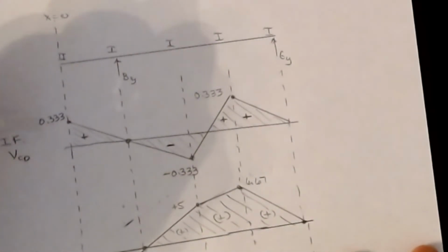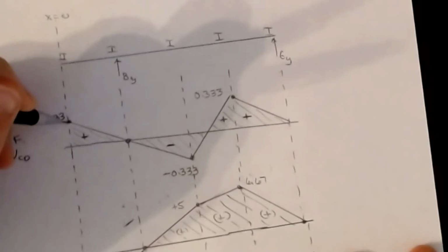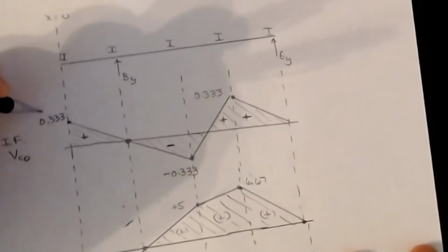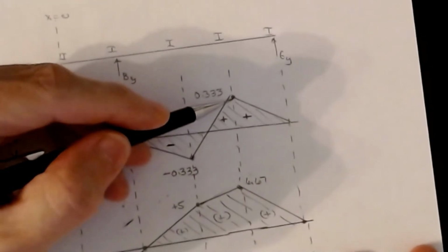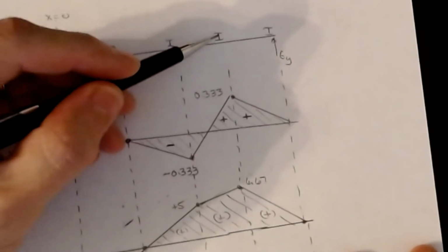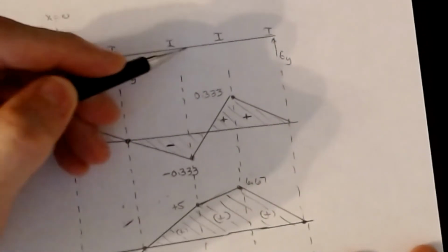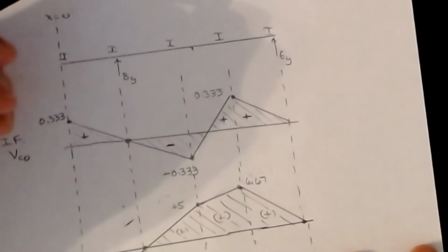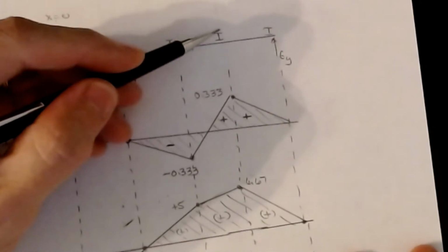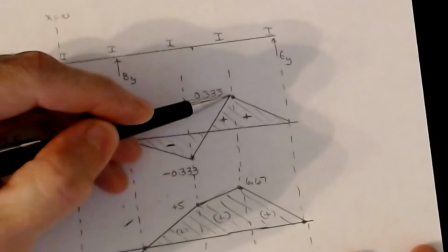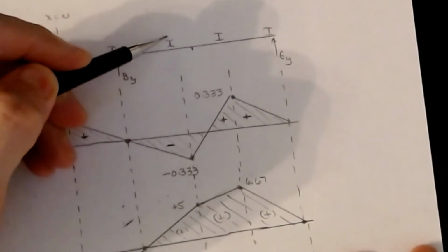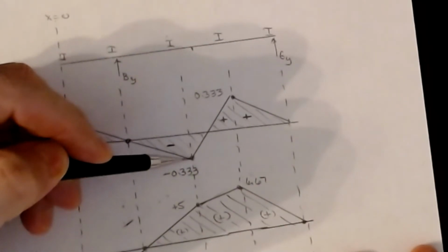So for shear, you can tell right off the bat that there are 2 places that get me the maximum positive shear. I can put the point load out at the end of the cantilever, and its multiplier is 0.333, or I can put it directly over that support that's 10 feet from the end. Now again, F is sitting here. Okay, so if we put all my point load here, I actually get a bigger shear value. But likewise, if I put it over the support to the other side of it, I actually get the negative of the shear, okay?